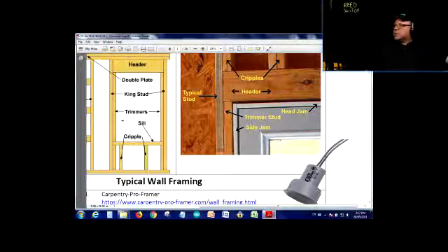The other mouse. This header plate right here. It's not really hollow inside. It goes all the way through. So there you have a lot of wood to drill through, and you should get a specific drill bit that's basically longer, so you can drill right through that and run your wires, right? So that's why you need to know this type of construction.